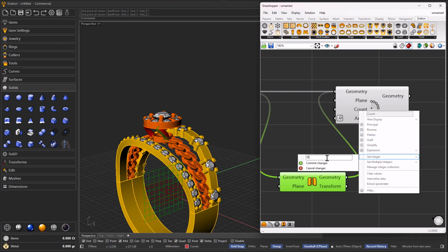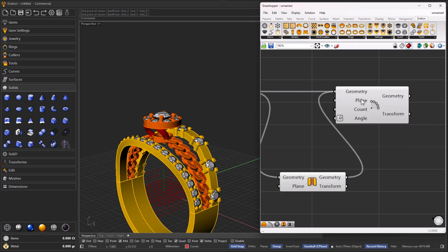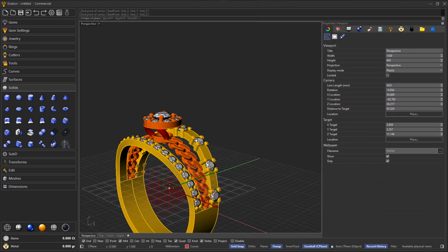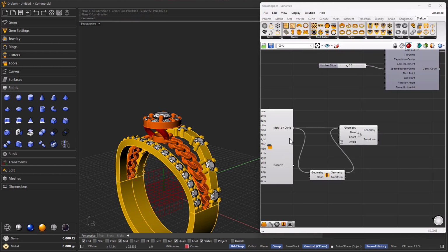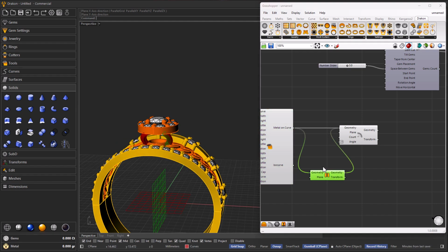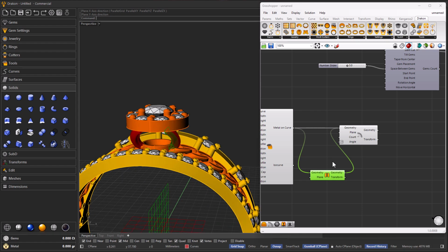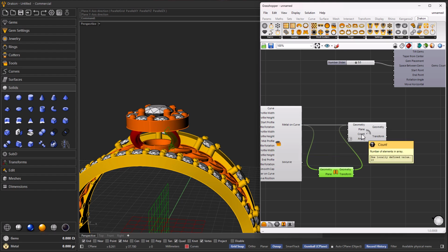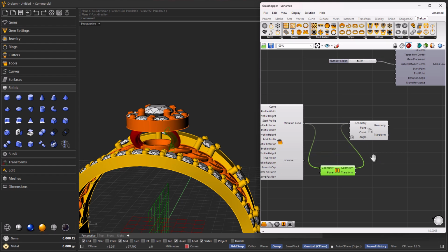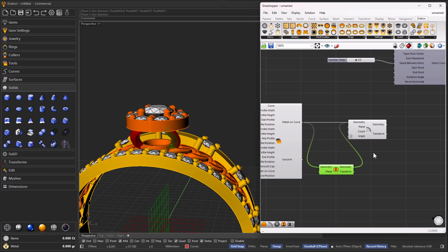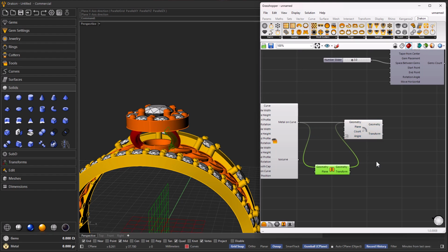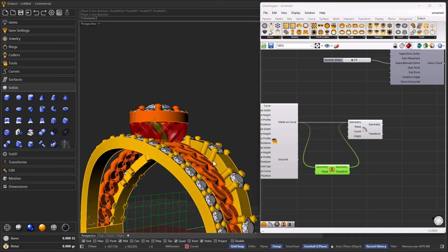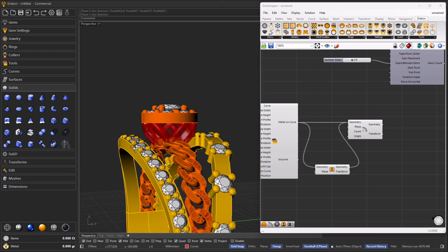What's going on here? Let me just check number of copies. Make sure the plane is the central plane, and okay, the mirror, the original, and actually I think what might be missing here is to adjust the angle. Yeah, because it was on radians and I need to put on degrees. So let me make sure I will set it properly.